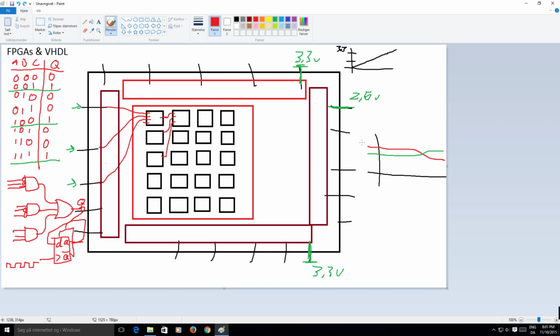The second thing is that the differential signal is also very good at suppressing noise, because usually you have these 2 tracks running right next to each other on the PCB. And since they're not really evaluated with respect to ground, but only with respect to each other, then if you introduce noise to one signal, say there's a little bump there, and this is extremely exaggerated, but so you get the idea. You can see here we're very close to the red line, but since the tracks run right next to each other, the same noise would appear on the red line, and the signals are actually equally spaced, even though we have the noise.